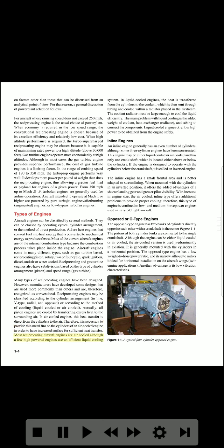Most reciprocating aircraft engines are air-cooled, although a few high-powered engines use an efficient liquid cooling system. In liquid-cooled engines, the heat is transferred from the cylinders to the coolant, which is then sent through tubing and cooled within a radiator placed in the airstream. The coolant radiator must be large enough to cool the liquid efficiently. The main problem with liquid cooling is the added weight of coolant, heat exchanger, radiator, and tubing to connect the components. Liquid-cooled engines do allow high power to be obtained from the engine safely.